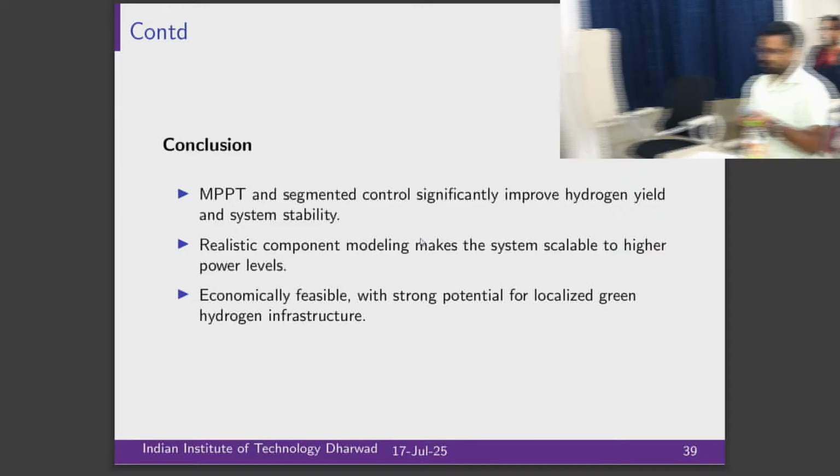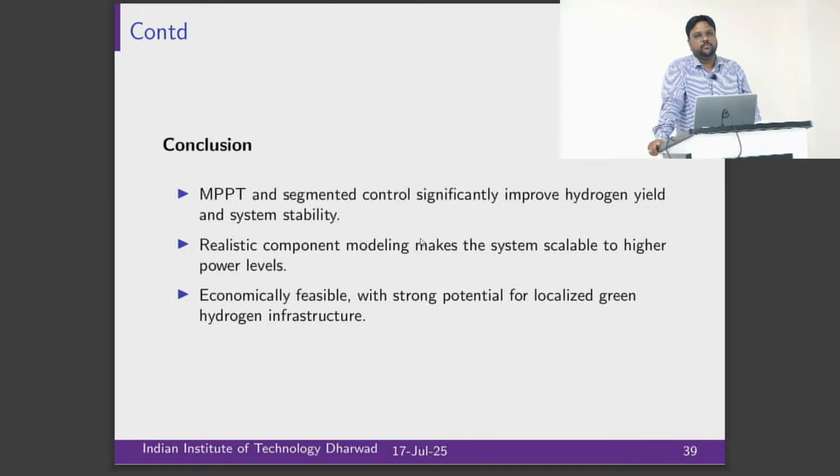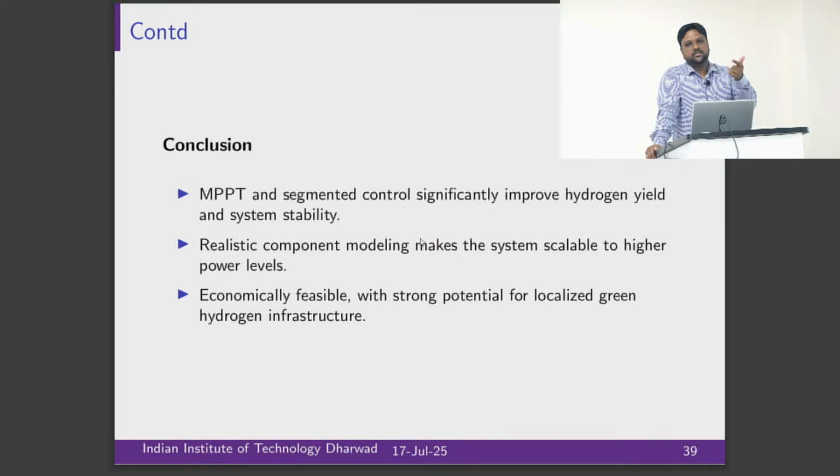Yeah, so the main two aspects differ between a hydrogen electrolyzer and a battery. One, I will again repeat that PQ curve. If I draw my P active power and Q reactive power axes, as I told, the electrolyzer can operate as a sink of active power, but it can both source and sink reactive power. But a battery, as we know, is a bidirectional device. It can operate in all four quadrants. That is one of the system characteristics.